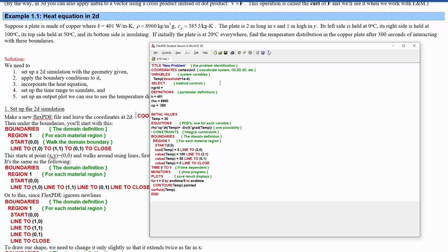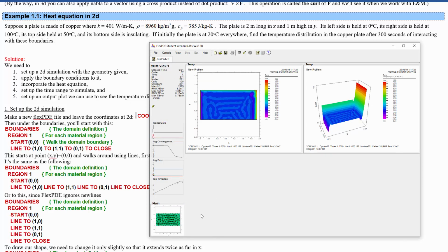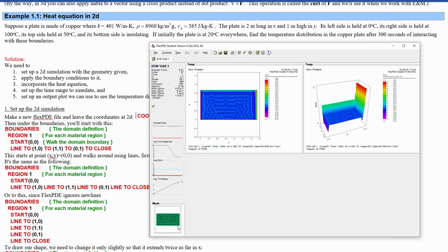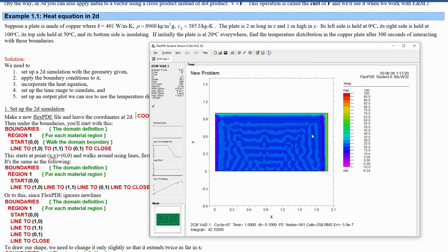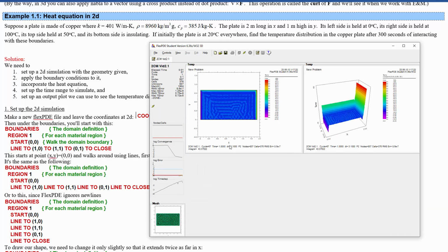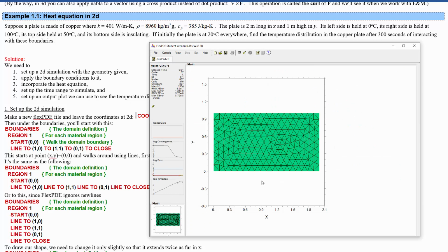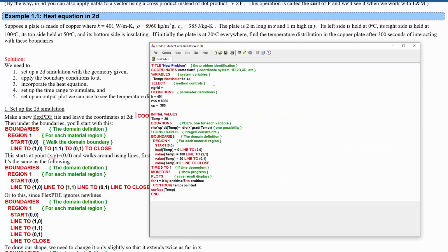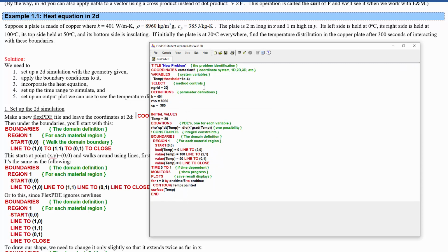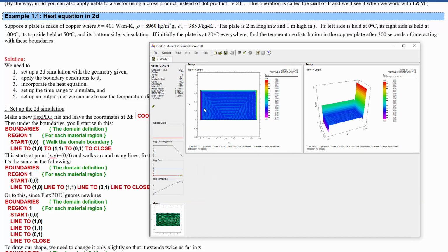So ngrid is equal to 10. We can see how high we can push this up. That seems about the same. Let's try ngrid is equal to 15. A little bit more dense, and we've got a little bit less weirdness there. Can we do ngrid is equal to 18? Looks good. So this is quite a bit more dense mesh. How about 25? Nope, not allowed. What about 22? Not allowed. 20? Maybe 18 is about the best as we're gonna get. 19? 19. 19 for this particular geometry looks like it's okay.